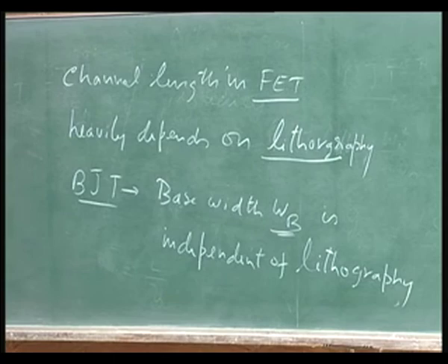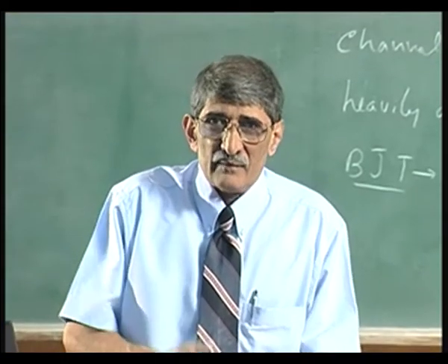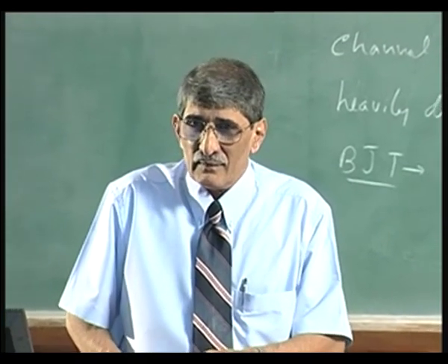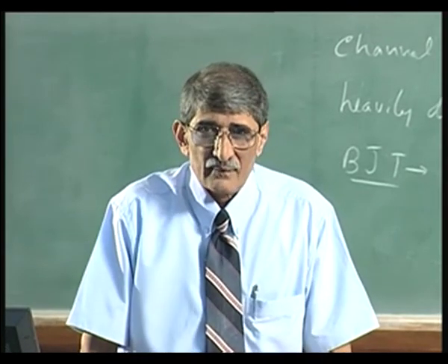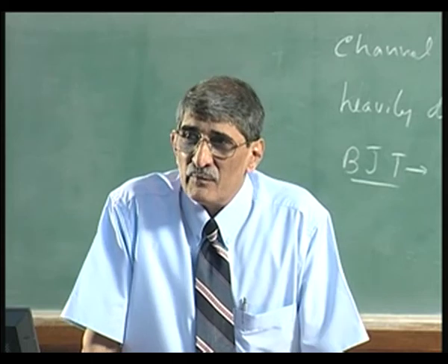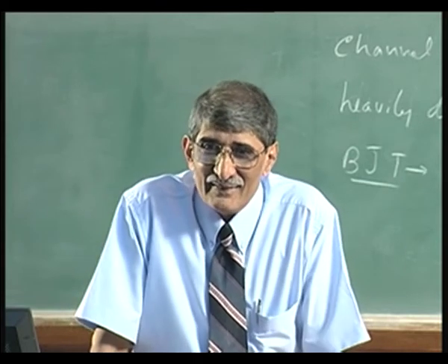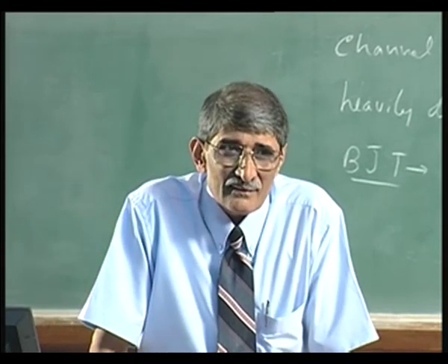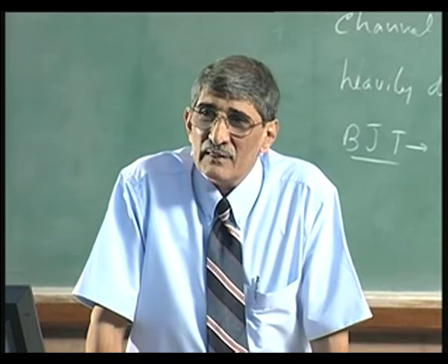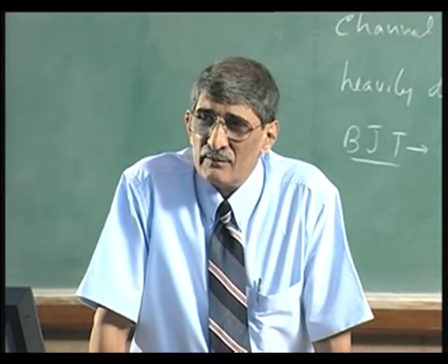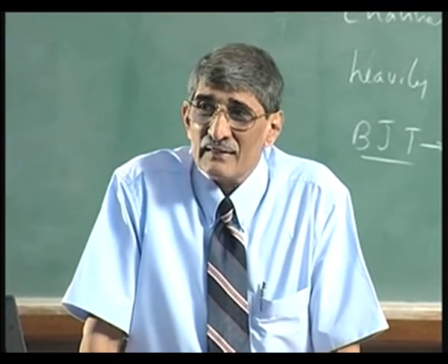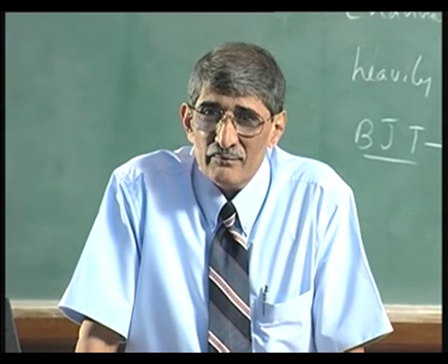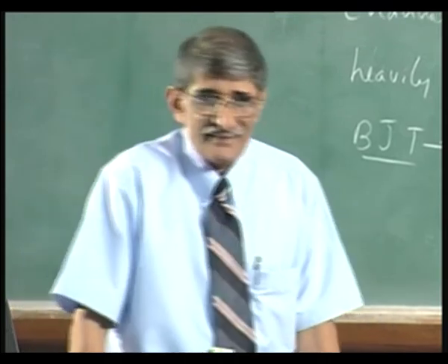when people are comparing the MOSFET and bipolar transistor. 1970s textbooks, if you open up and see, it will tell you that MOSFET is lower, because at that time the lithography was 5 micron, 10 micron, that range, and the base width that you are going to get is 0.5 micron very comfortably.